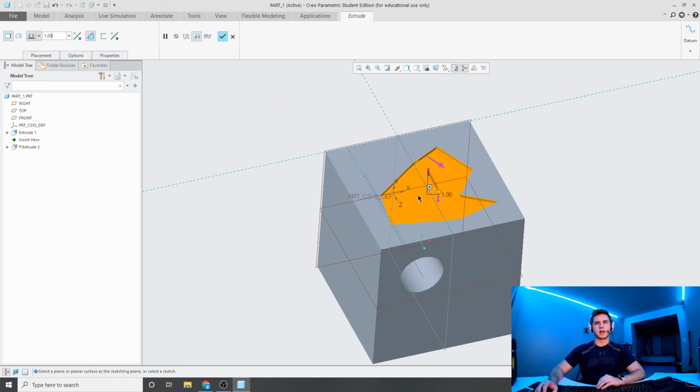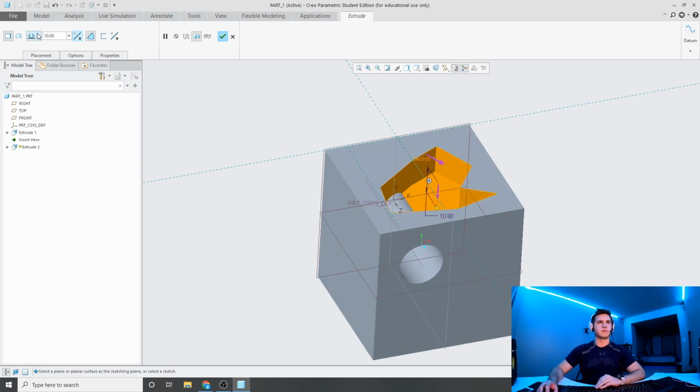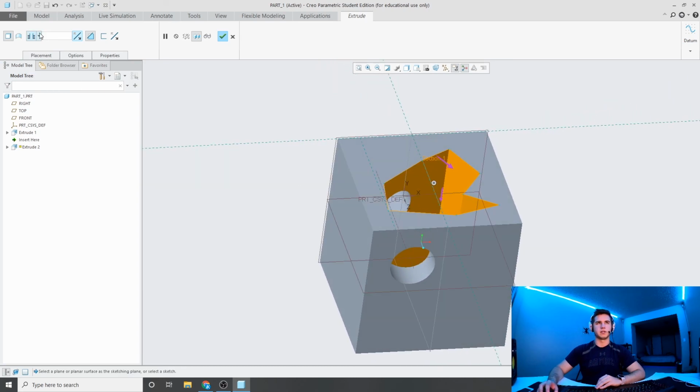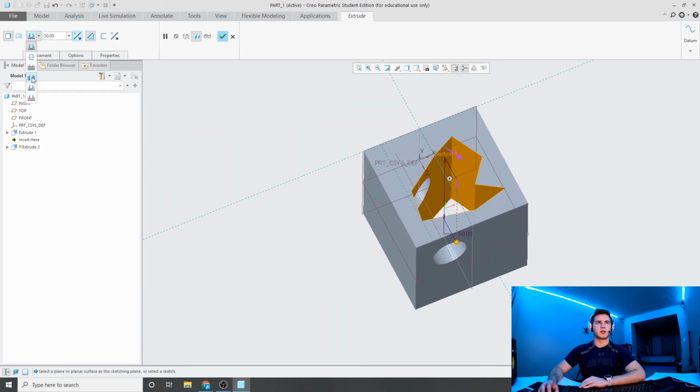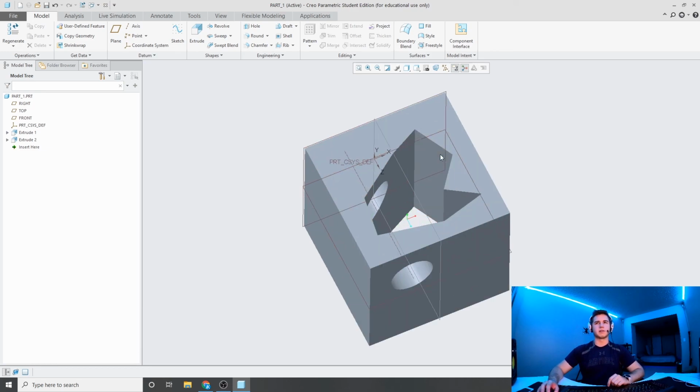So I'll bring up another option here. Now that we're cutting, we can just use the dimensions like we had before. You can put in a dimension, and it'll cut down that specific dimension, but in here another two options popped up. This one will extrude all the way through the part, or the direction that you're going, so you see it cut all the way through. You could just as easily cut 50, but if it changes at all, having this can help as well. So we'll be done with that. We'll click OK.